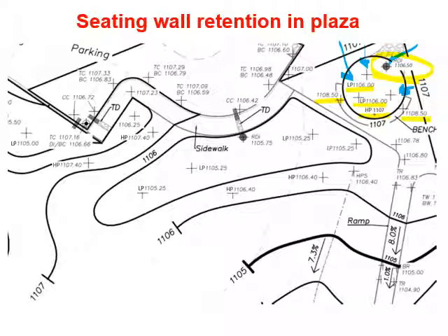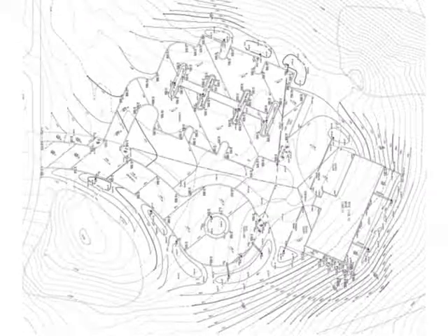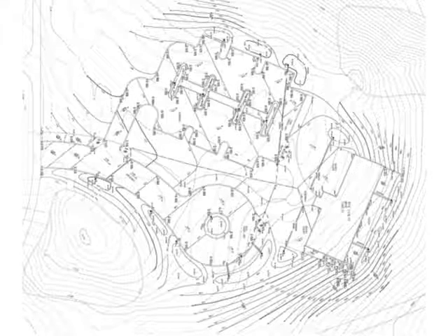Could be that we can actually sink this bioretention area down further, because by sinking that bioretention area down further, it makes it easier to make sure that that raised drop inlet is half a foot below the high point. So it's not unusual to simply have the edge of the bioretention area have a vertical wall that's about a foot deep or so. So these are the basic techniques that you're going to use on your plan.